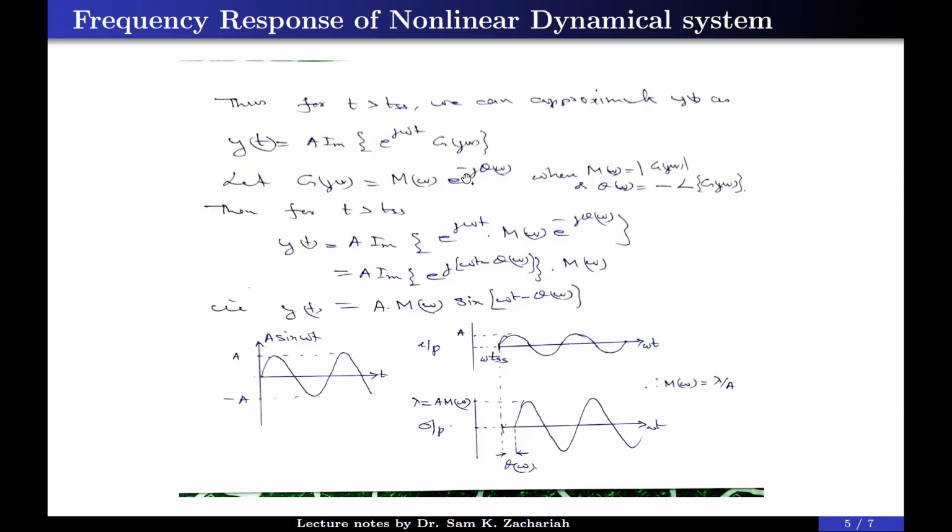For understanding, you can replace minus minus by plus plus, but I explicitly define theta omega as the phase lag instead of phase lead, because in all physical systems we normally see phase lag. So I define the argument as a lagged phase instead of a normal lead phase. That's the only purpose behind this.